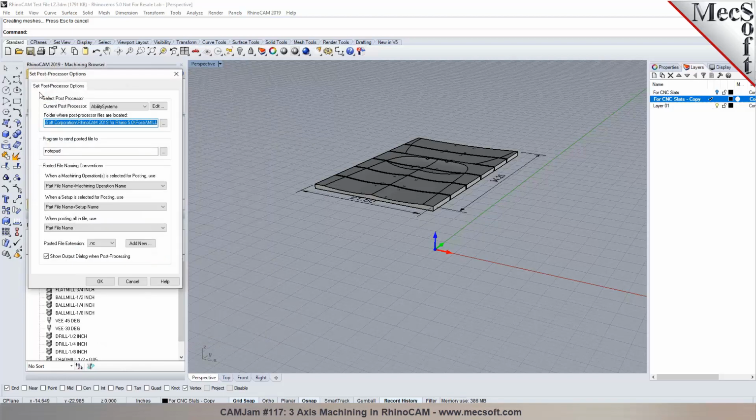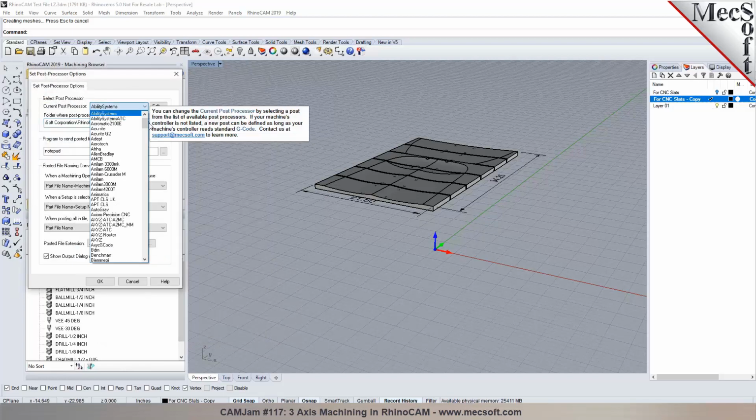The next step is selecting the post processor. This would be the CNC machine tool that you're going to be outputting the code for. Can you see if you've got Laguna's IQ Pro? Yep, we have several different posts for Laguna in here, and you'll find as you go through the list, the posts are listed either by the name of the machine or the controller. So you can see there's one for the BNR controller IQ. We also have several other Laguna posts in here, and I can bring them in as well. Okay, great. So if you're using the BNR controller, it says Laguna BNR with the IQ.